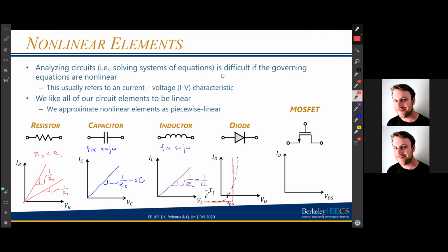well, I guess I've drawn my diode turn on voltage a little differently here. And so if I said my VD0 was there, my turn on voltage, then I would approximate it like this, right? Where any voltage above VD0, any current through that diode will give me the same voltage drop, VD0. And so, like I said, this is a piecewise linear function.